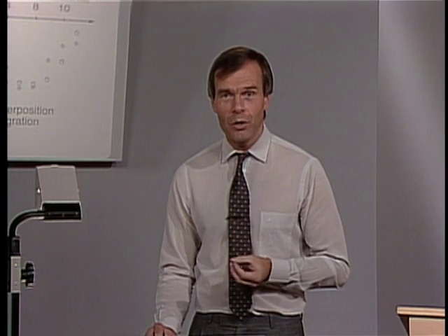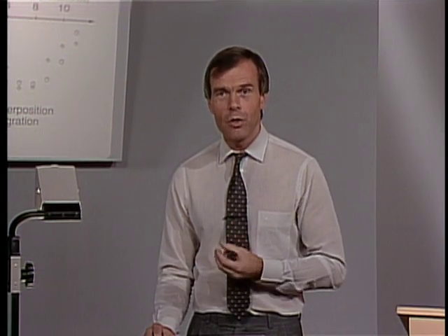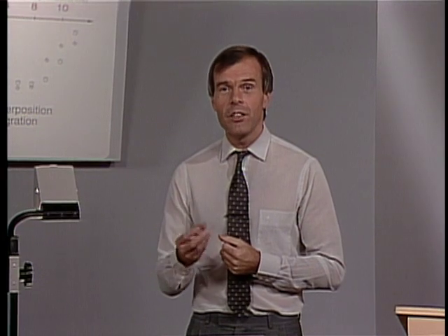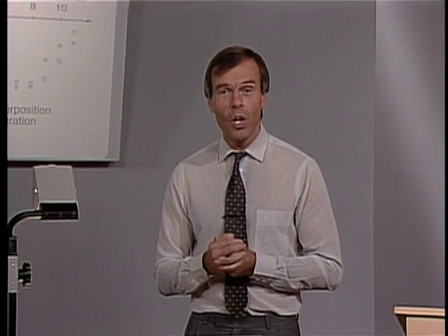However, I believe that the mode superposition solution is of much value in the initial design analysis stages when you want to obtain fairly inexpensive solutions for the response, and you want to just understand how the system that you are analyzing and designing acts. The mode superposition solution really yields relatively inexpensive response solutions of the system, which may be very helpful in the initial design stages of that structural system.